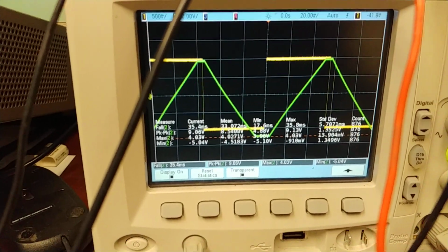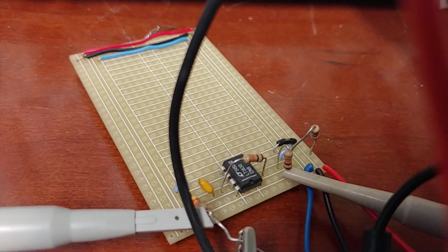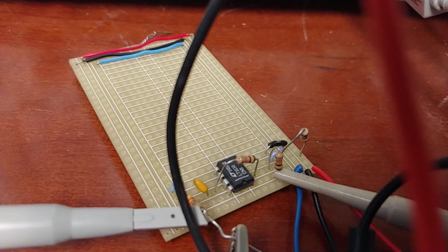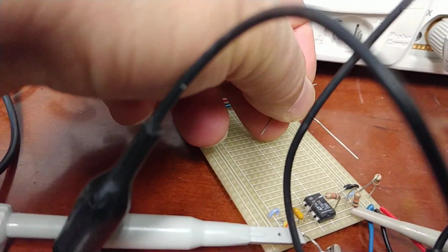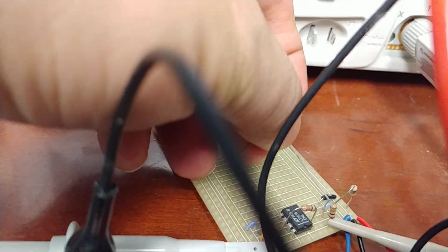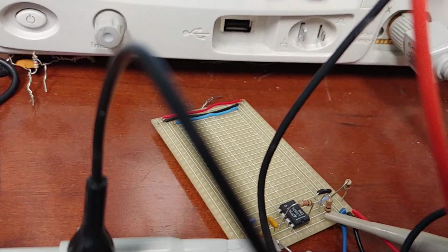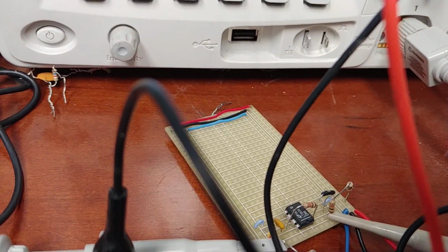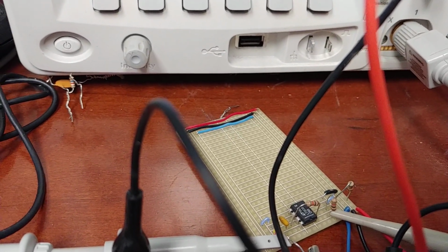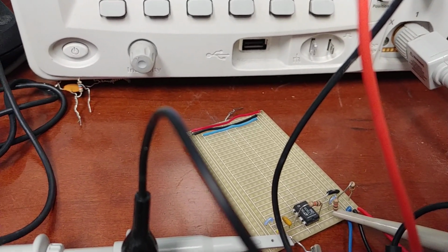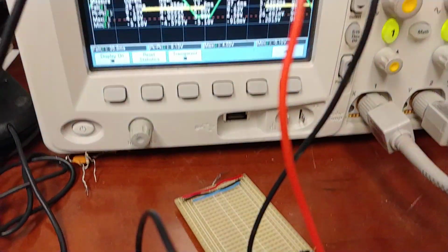But it's good though that I've tested this bit by bit, because I thought that this blue line connecting ground was connecting ground to the V plus of the second op amp, and it wasn't. And boy, was I getting some weird results. So if I had assembled the whole circuit, it would have taken me forever to find that mistake.